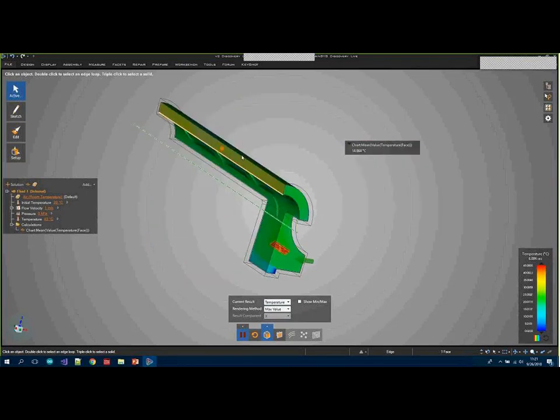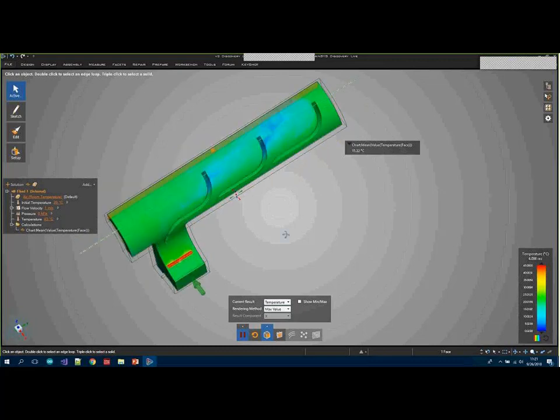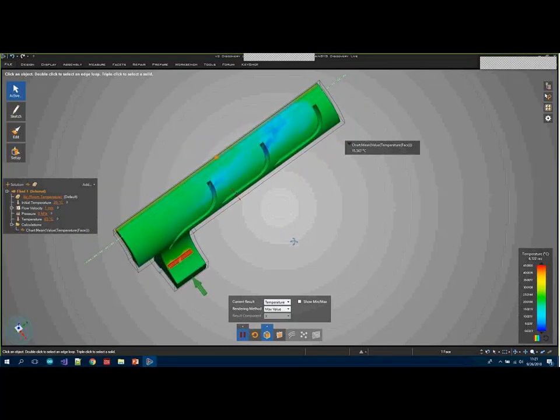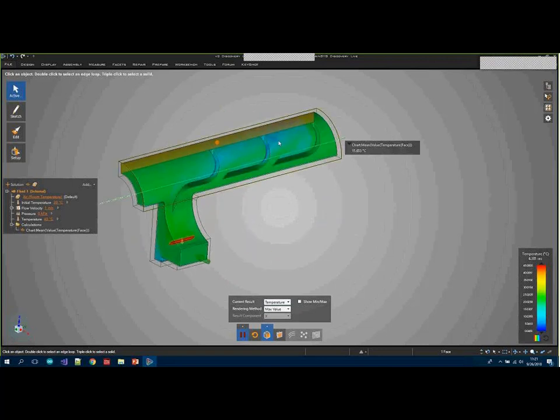It's taking the average across this entire face. So as we can see, there's still some areas here that are not all uniformly at the same temperature. But eventually, as this simulation continues to run, if we let it run some time longer, I assume that we'll reach a steady state. And we're sort of converging here on temperature. The temperature has stopped increasing quite as quickly as it was before. So we're getting there. But that's essentially how you would achieve this type of a measurement or calculation.